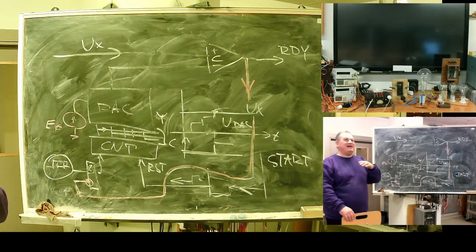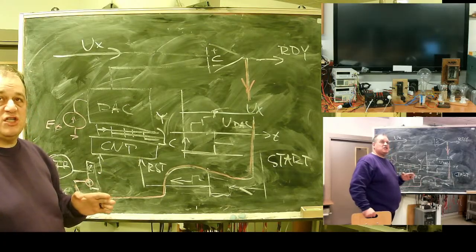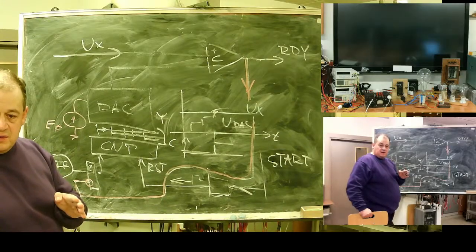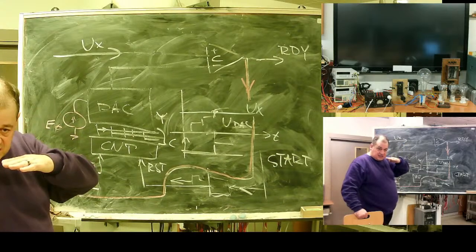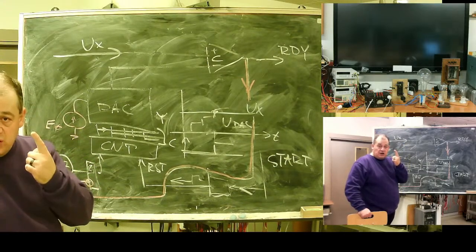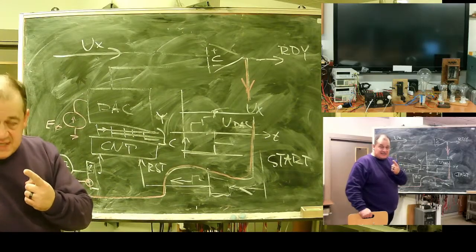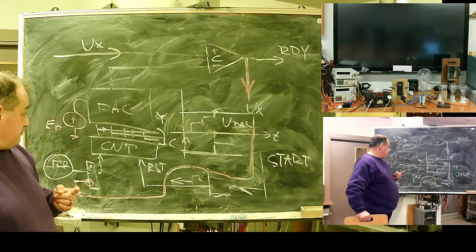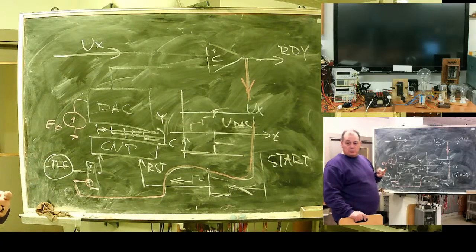Producing an array of R-2R ladder resistors and one operational amplifier is much cheaper than an array of resistors plus a set of precise operational amplifiers. So they are cheaper and they are available up to 18 bits.